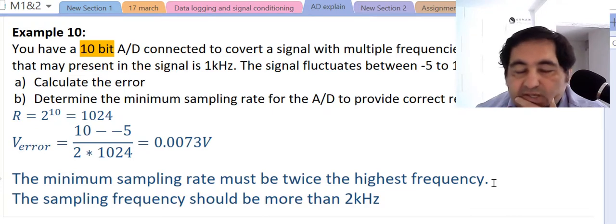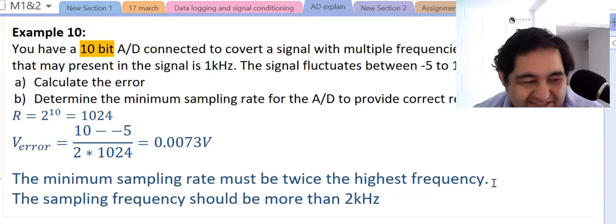I would say, if you have a sine wave, especially if you wanted to do things like Fourier analysis, that at least we need something like 16 points, which is much higher than that, to have a good understanding of the signal and avoid getting unwanted noises.